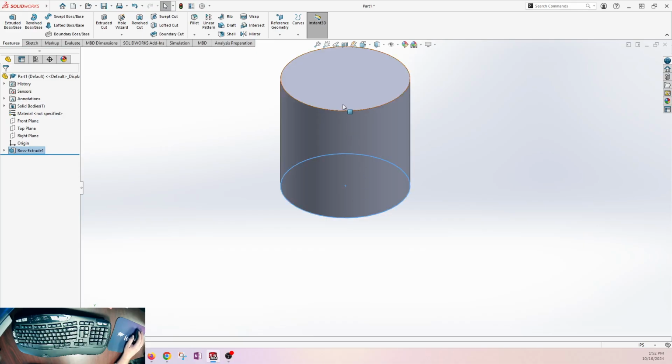Okay, this surface or that plane are not going to do you any good for a revolve cut if you want it to be around the circumference of this cylinder. What you need is a plane that passes through the axis. But the axis being on that plane is important. So the front plane would work, or the right plane in this case.